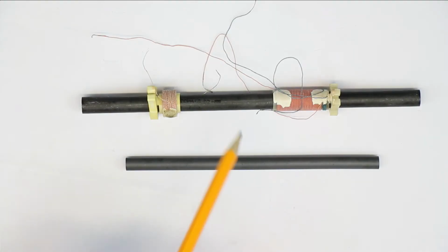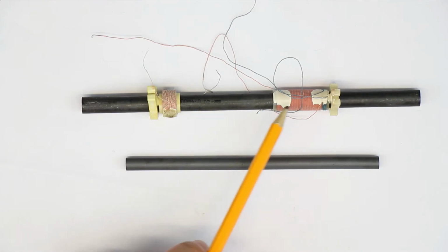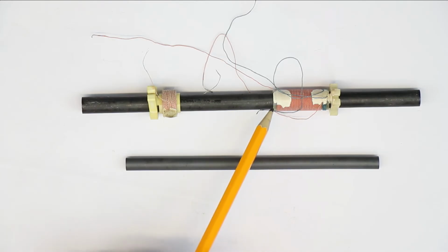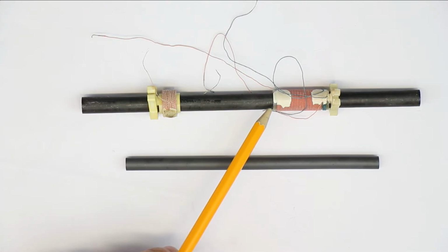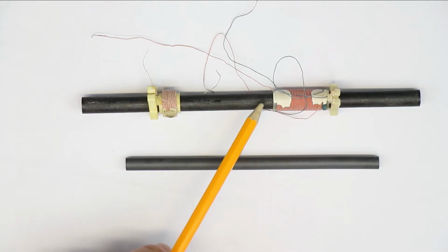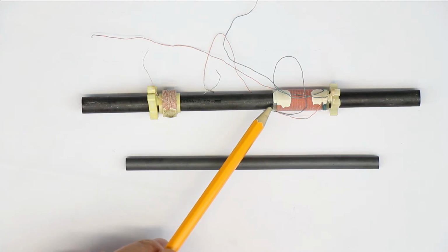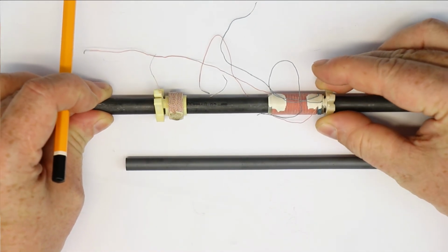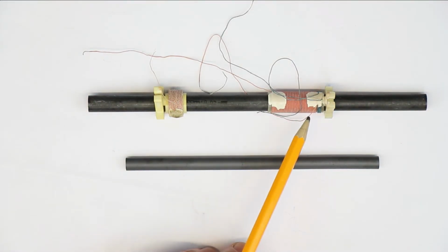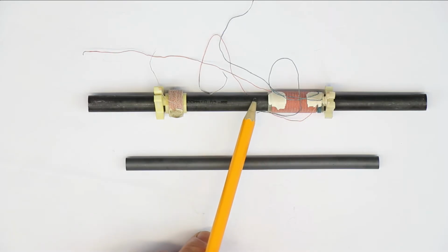So in every good Ferrite-Rod antenna that you see, you will notice that the reception coil, or coils if there are more than one, are not wound directly onto the Ferrite-Rod, but there is always a kind of carrier material that the winding is wound on. The reason is manifold. First of all, by using a material as a kind of spacer, you can easily shift and thereby fine-tune the coil, because the inductance that you get is also sensitive to the position of the coil.